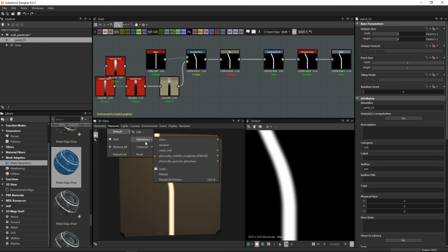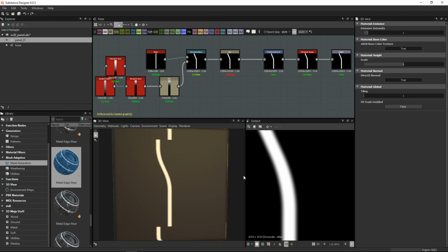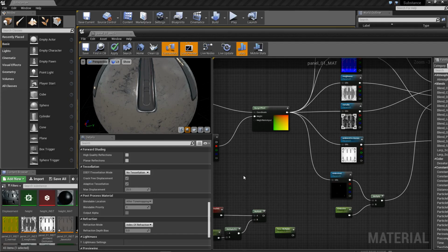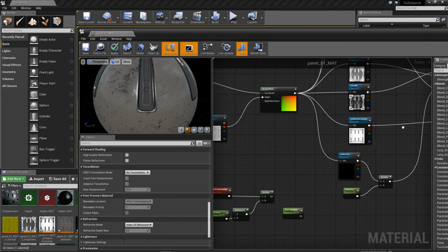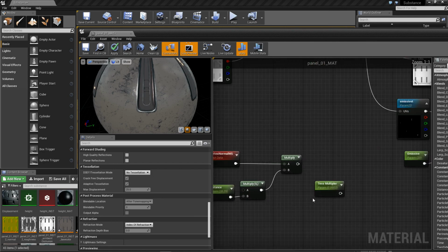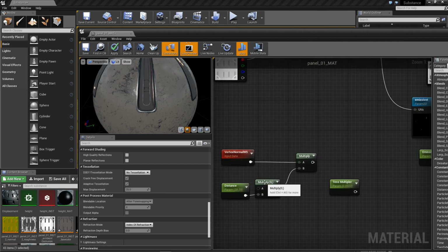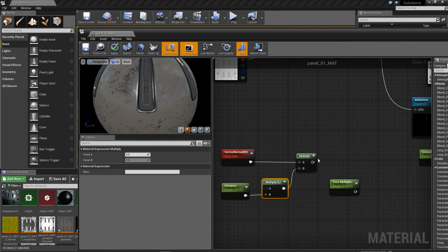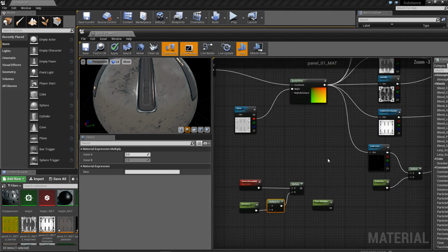In the materials definitions, you go to physically based metal rough, you have a tessellation and a parallax. So what I'm using in UE4 is the equivalent to this parallax occlusion shader. And that's my material setup here. Here you can see that I was actually setting up one to work for displacement as well, but I ended up not using that.